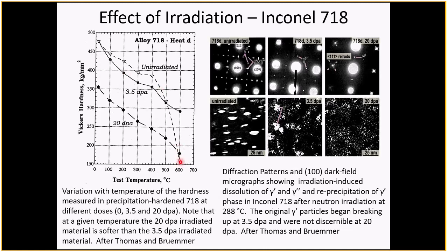because at high temperatures, it doesn't really matter. The unirradiated and the irradiated are the same. And that's where, at high temperatures, in effect, the material doesn't know it's been irradiated. The thermodynamics is governed primarily by all the vacancies that are created, the thermal vacancies which are created at the high temperatures. So from a diffusional point of view, the material could care less whether it's been irradiated or not.